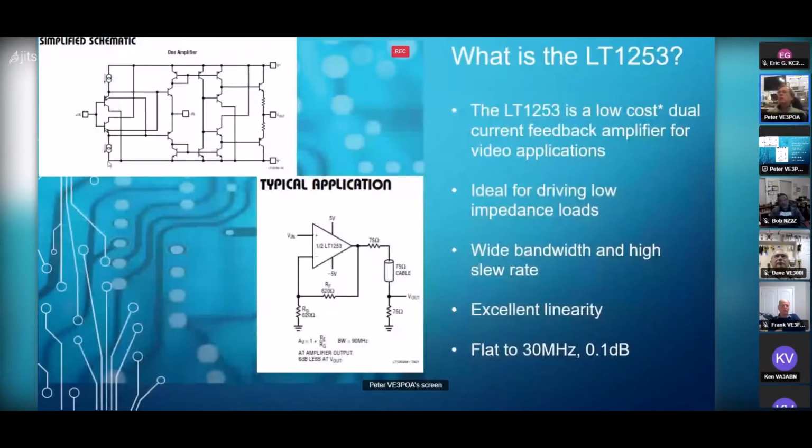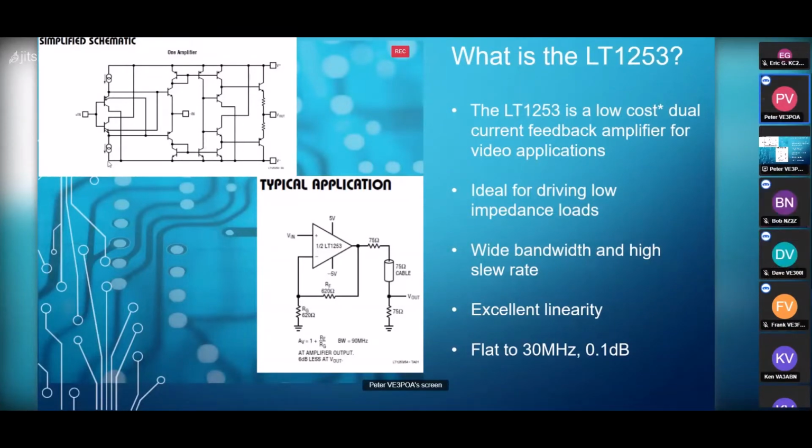So the LT1253, it's a low cost, depending on how cheap of a ham you are, that is. Dual current feedback amplifier for video applications. So if it can do video, it should be able to handle our 1 to 30 megahertz range without any effort.